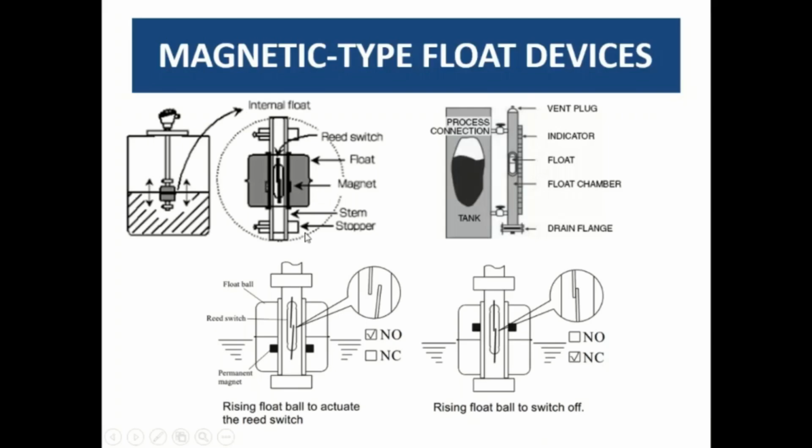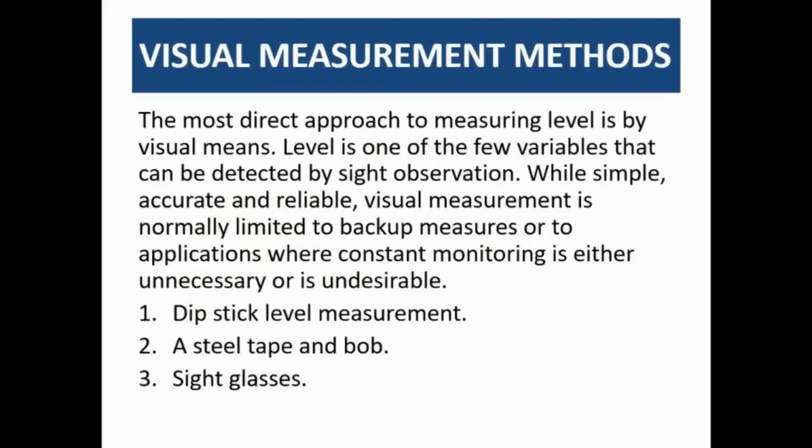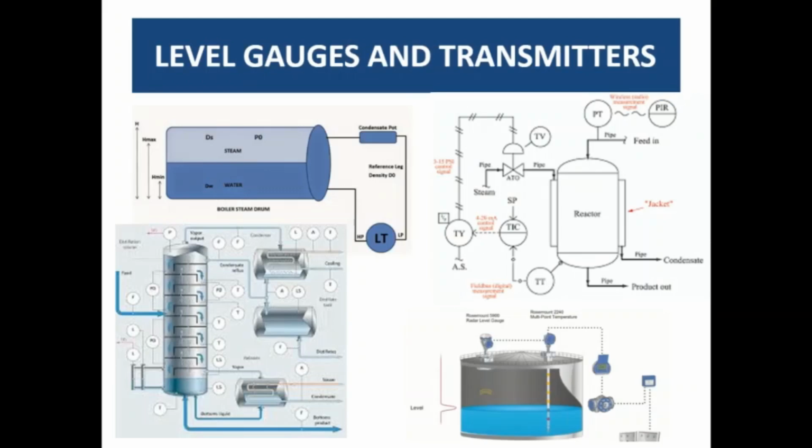It is very important that you know the range of your process, according to which you have installed it within a particular process. As I explained at the beginning of my lecture, in a distillation unit you don't attach the LT over the complete column. You just need to understand the range up to which you need to fill this vessel.